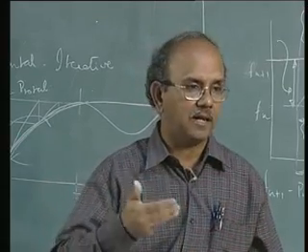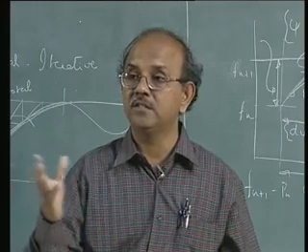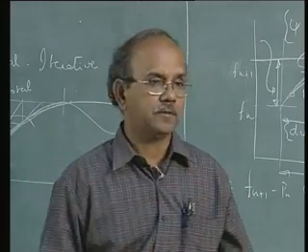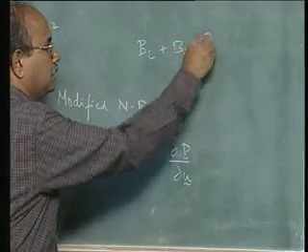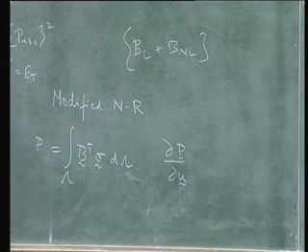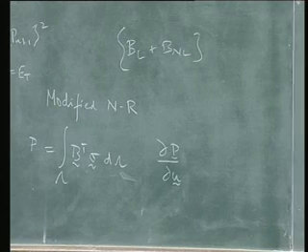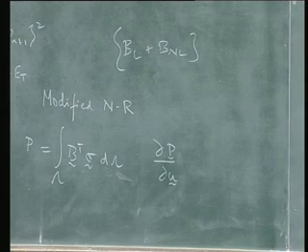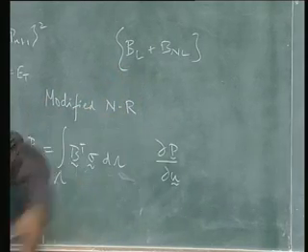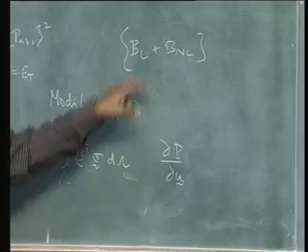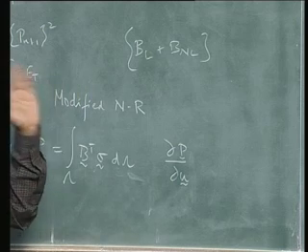People call this BL. This B itself may undergo changes, and B has to be written in terms of BL plus BNL. That is basically because the strain displacement terms you have are ones where only linear terms are considered. Nonlinear terms are not considered. So we stick to this. In other words, for small deformation, not moving into finite deformations, this BL is enough to define, though we may move into the nonlinear regime of the stress strain curve.